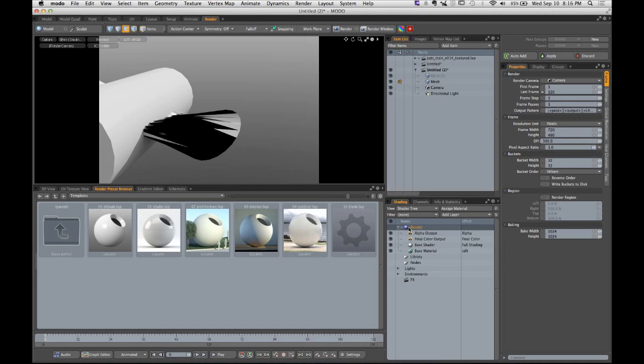And I simply clicked on that purple sphere. After you click it, all of the properties for your render are going to appear to the right in the Properties tab. The first vertical tab in this environment says Frame. And about halfway down, you can see a frame width and a frame height. Please change this to 1280 by 720, and you're ready to render.